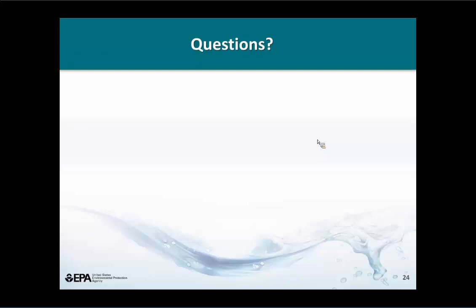Does SWMM have removal efficiencies built in for different green infrastructure technologies, sort of a database of what you could expect to be removed if you use a given method? Yes and no. When you put in your LID, you put in different thicknesses of soil layers and storage layers and so on. This is very well handled in the LID portion of reference manual number 3.